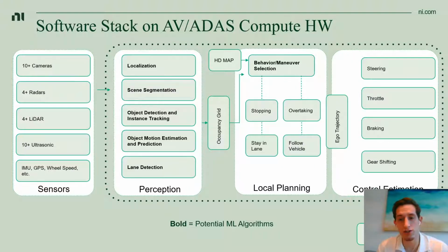So what's interesting to note here is that within that perception system, you may see a lot of GPUs, neural net accelerators, machine learning algorithms that run there. In the planning system, you may see CPUs and FPGAs, real-time CPUs, and in the control system, you see largely FPGAs and ASIC systems for actually doing that. So a mix of different computational accelerators to actually compute these things.